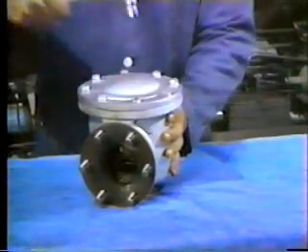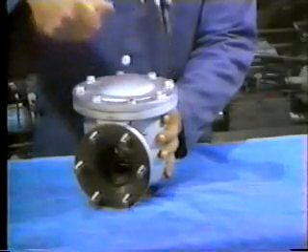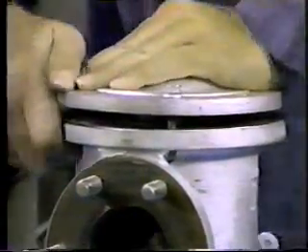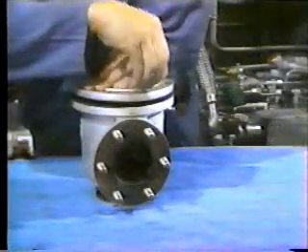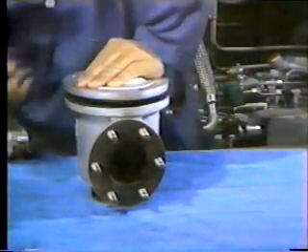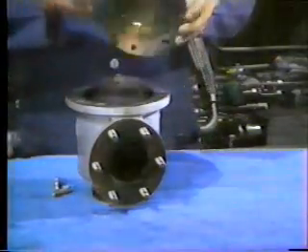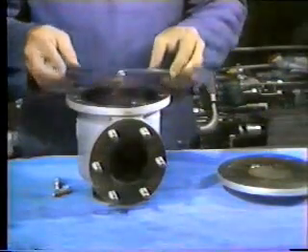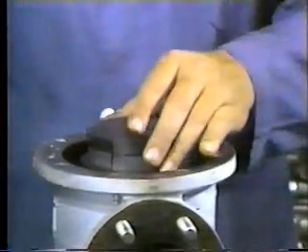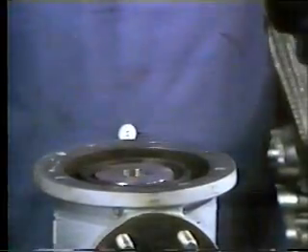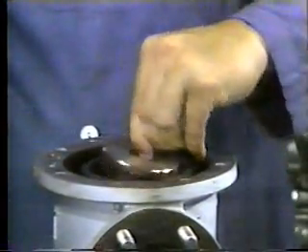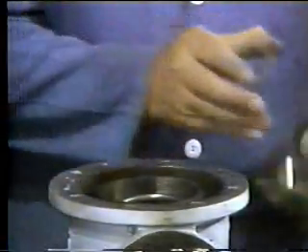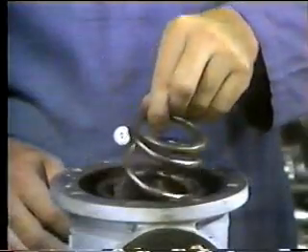Loosen the 8 bolts on the cover a little at a time and verify that the piston is coming out of the housing. Remember, the piston is spring-loaded and will force the cover away from the housing as the bolts are loosened. As you remove the cover, remove the gasket and discard. Carefully remove the piston from the housing. The spring seat and altitude shims can now be retrieved from the housing. Remove the spring.